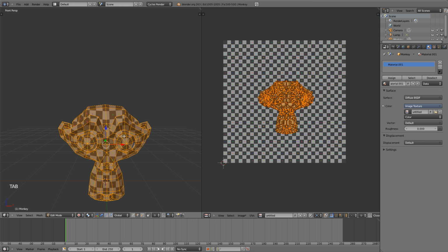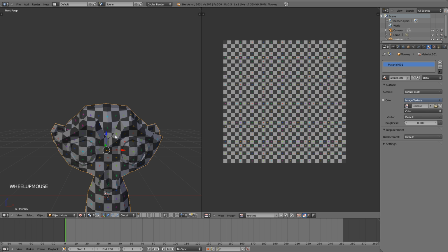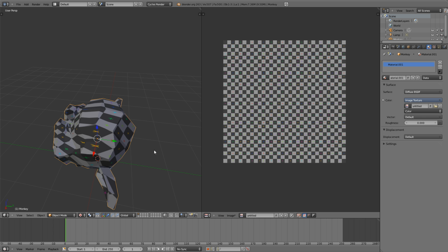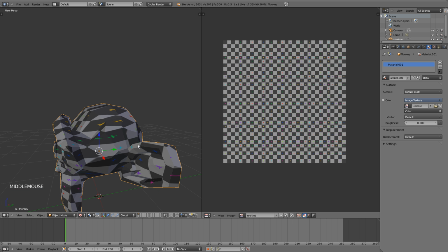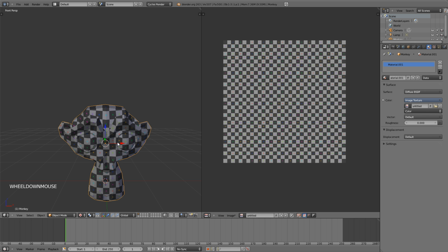Now it's important with any face model to not add seams directly on the face or the main features such as the eyes, the nose, or the mouth, because you will get some seam marks on it and it won't look good. So a tip is to keep the seams always to the back or on the sides. Just try to keep them out of the view of the face or whatever is going to be in focus